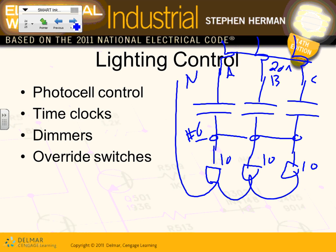Now, controlling this contactor: your option number 1 for controlling it is photocell control. Your option number 2 is a clock. Option number 3, dimmer, and not really a whole option, override switches; you can also have an override for the auto, if you turn them on at a different time.